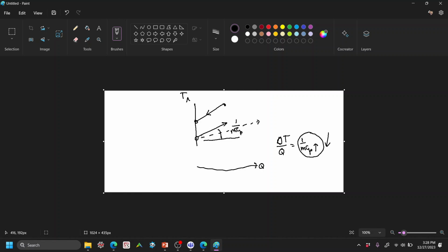So you can recover this heat, for example, as much as possible, in such a way that all of the energy can move to these streams. But you have to pick this stream in such a way that when you put the energy, its temperature doesn't go up like that, because this is then going to be the violation, because we have a very small delta T. Delta T is smaller than this delta T.